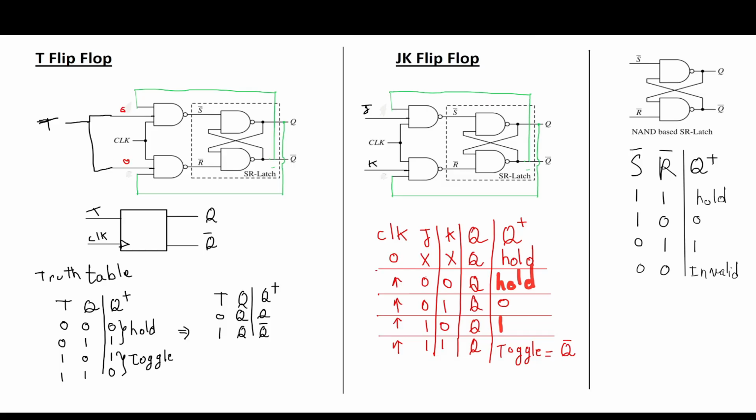And also we'll have 0 here. The current state of the system, we're assuming it's 0. So Q is 0. So we want to figure out the next state after one step. So this 0 will come as an input to this NAND gate. And also if you follow this green line, it's a feedback input to the 3-input NAND gate.